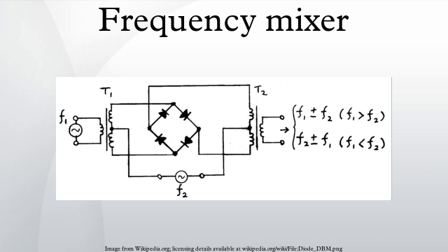Types: a device that has a nonlinear characteristic can act as a mixer. Passive mixers use one or more diodes and rely on the nonlinear relation between voltage and current to provide the multiplying element. In a passive mixer, the desired output signal is always of lower power than the input signals. Active mixers use an amplifying device to increase the strength of the product signal. Active mixers improve isolation between the ports, but may have higher noise and more power consumption. An active mixer can be less tolerant of overload.